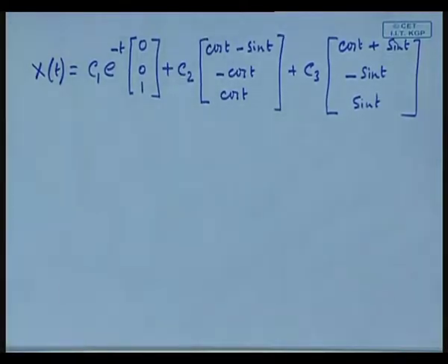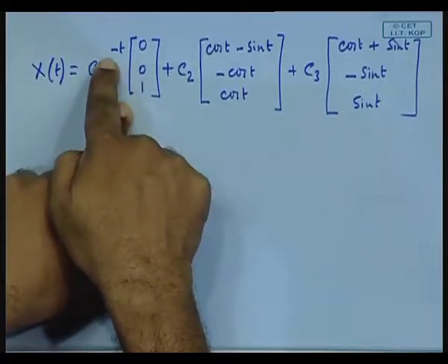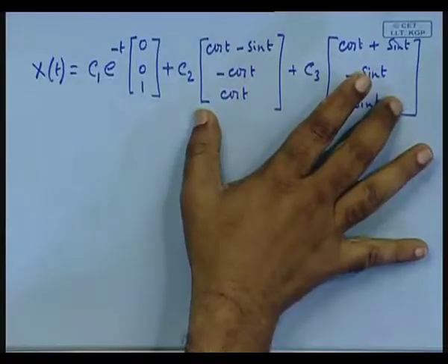Now, let us figure out what will be the behavior in the 3D state space. Yes, now it is interesting. Why? Because there is an eigenvector which is associated with a negative eigenvalue. A negative eigenvalue means contractive. So, there is an eigen direction, the z direction, along which it is contractive. So, any deviation along that will be exponentially decaying. But if there is a deviation along the other direction, what will happen to that? It will not decay.